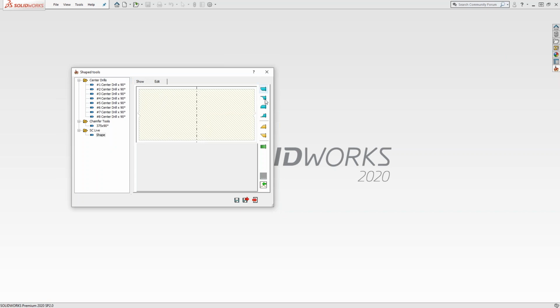So you'll see on the top right here, we've got all these building blocks to build the shape of your tool. You start from the tip and you go upwards. So let's say we were going to build that corner round tool. I would choose this concave shape, or a torus, I guess it's called, so you can get the bottom tip of your tool. There's your corner round right there. Obviously, that's not going to end at that kind of infinity point there, so we need to add a little bit of a cylinder. And then we can add another cylinder to represent the shank.